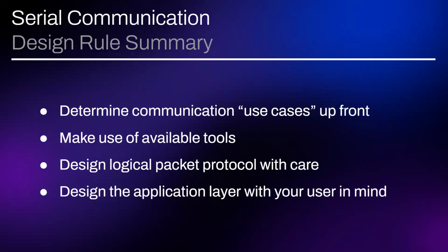Almost the only one I'm waiting for is processor and memory to talk to each other in serial too. That hasn't happened. I think the only analogy is that there are some signaling technologies that bundle up more than a single bit. It's not truly parallel. What he's saying is we used to use parallel ports a lot more often, where if you're doing an 8-bit transfer, you have 8 lines going across and usually a clock line as well. And there are issues with it: if you have a 1 here and a 0 here and you're switching one, it can flip. It's called crosstalk.